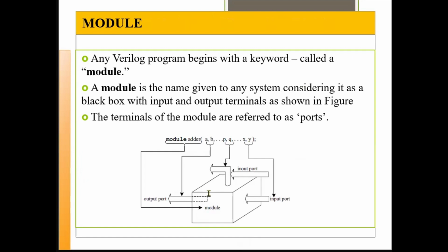two modules. One is the main design module. We can call it the design module, which describes what is there in the particular logic. And to test that particular logic, we are going to use another module called the Testbench module. So the Verilog program is divided into two, where we have a module which describes the circuitry, and to test the particular module, we have the test bench. So, two programs are required.